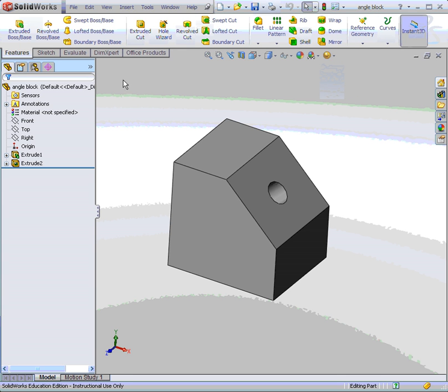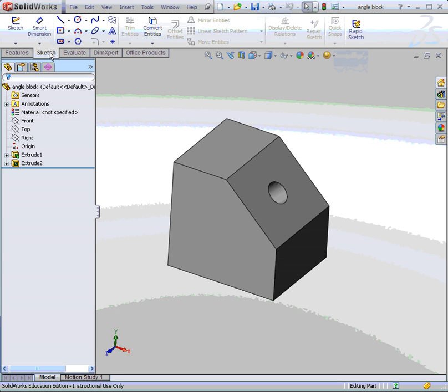The other most often used menu is the sketch tab, where we will create sketches which will then be extruded, applying dimensions, creating lines, and geometric shapes such as rectangles and circles. SolidWorks is very good with all the tooltips that appear as you approach an item. It will highlight and tell you what it does. Convert solid, selected model edges or sketch entities into sketch segments.